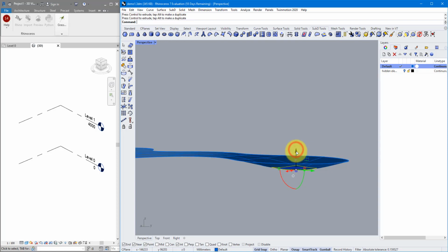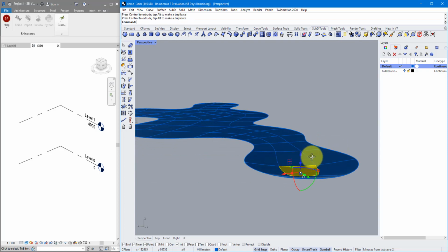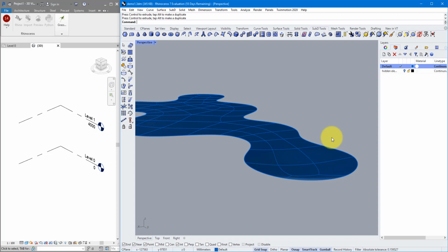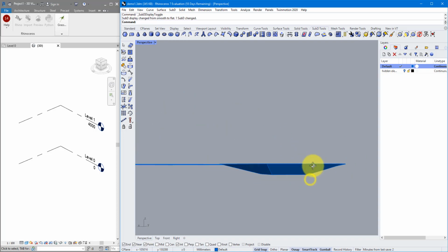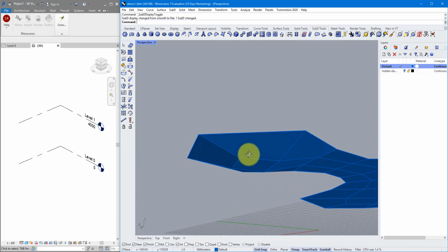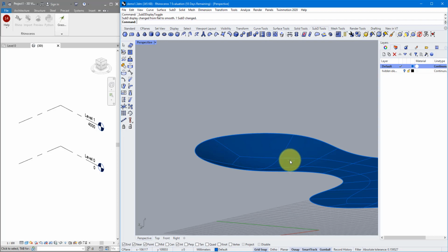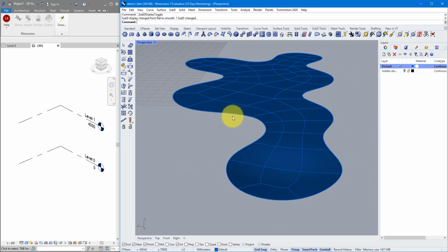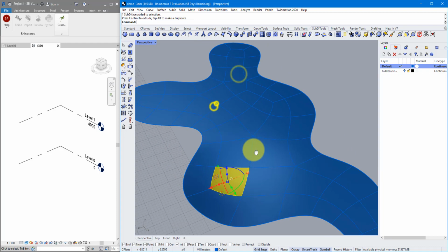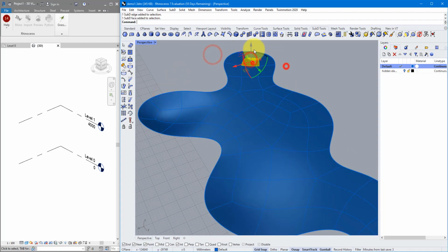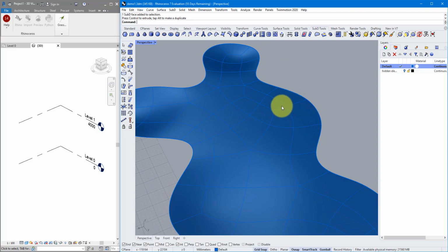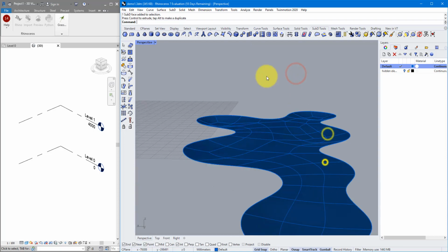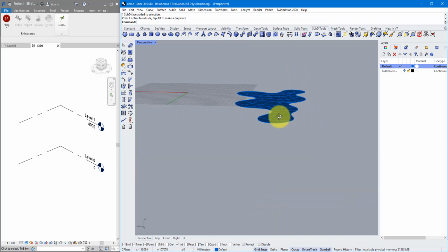You can see it's very easy to have curvature integrated into our form now. If I now press Tab to see the mesh, you can see that mesh surface has been pushed down. And now when I press Tab again, that whole thing has been smoothened on the fly for me. Let's do the same now for the other 5 circular areas of this form. This one is a bit special. We have to select maybe 3 surfaces instead of 1. So Control Shift and then 1, 2, 3, and then drag all of them down. Here we go. That's a much more interesting form already.